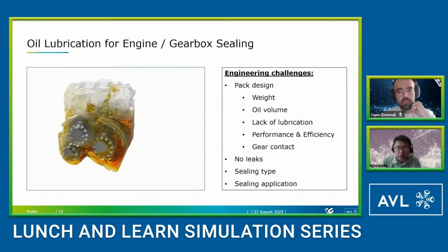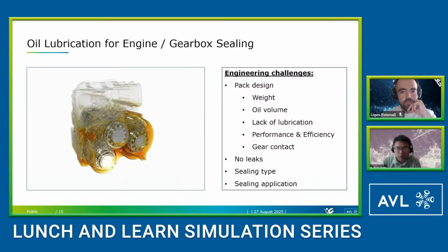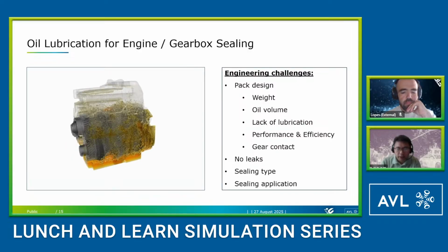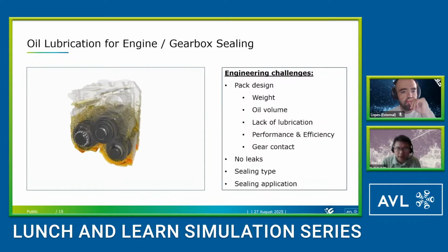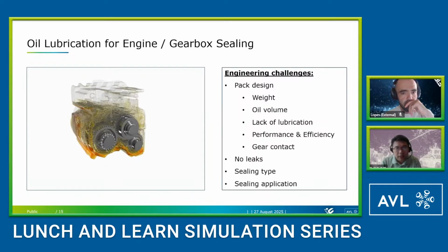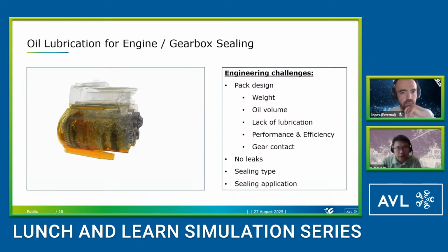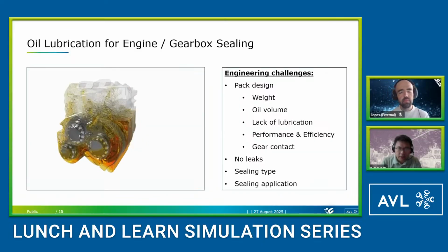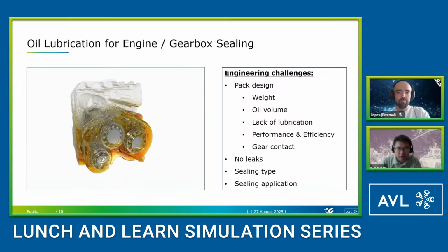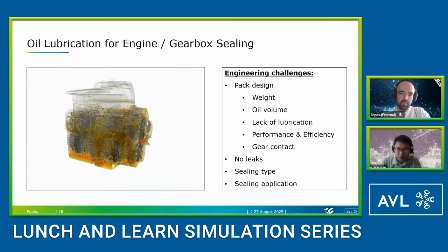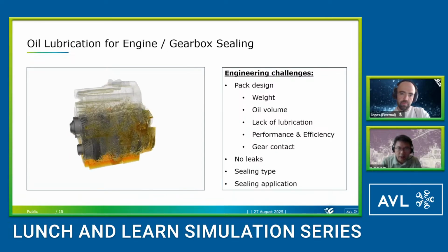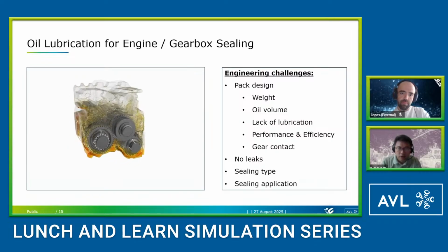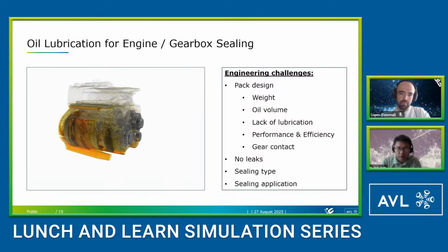In this simulation, we only need to load the surface. Compared to traditional CFD, we don't have to generate any sliding mesh or any mesh like that. So this saves significant time. Traditional mesh-based CFD typically takes several days or even weeks to generate the mesh for this kind of simulation. PreonLab just takes a couple of hours to load the surface mesh and set it up. Then you can initialize the oil volume and start the simulation. So it's quite time saving compared to traditional CFD.